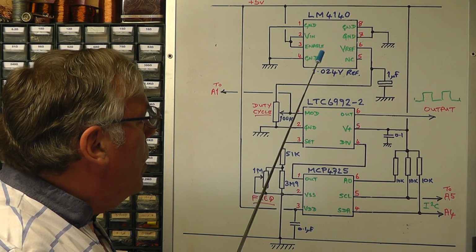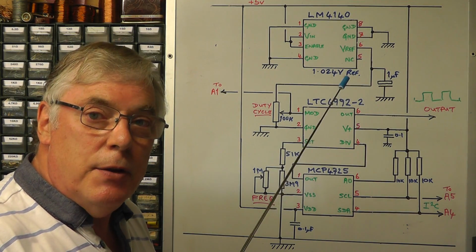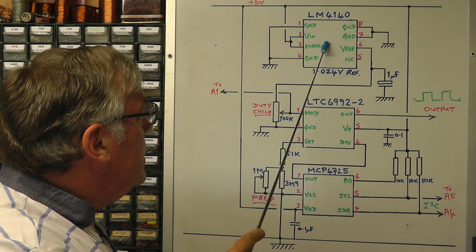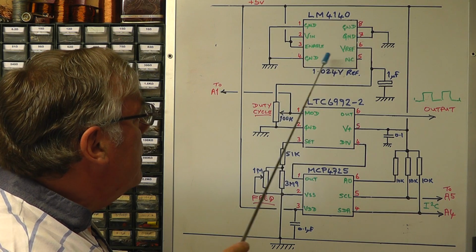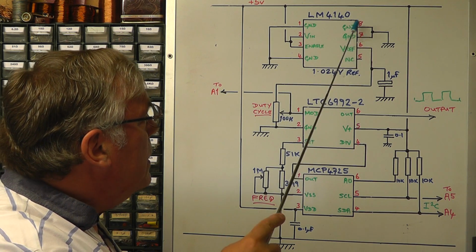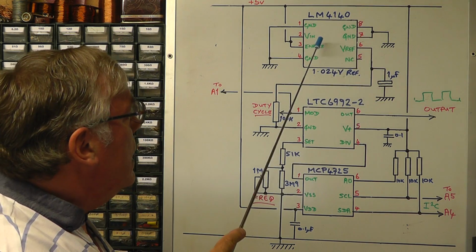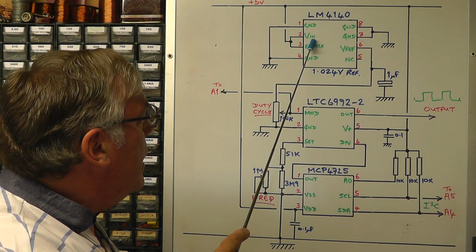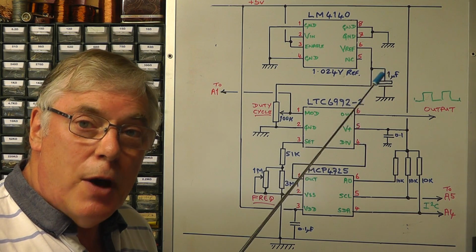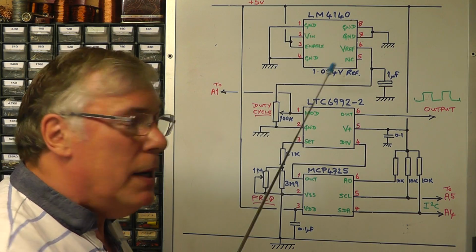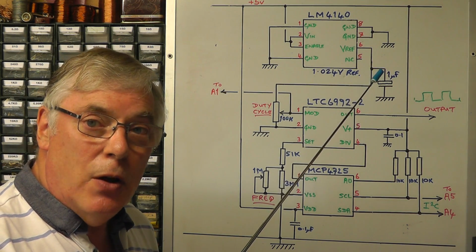Right, here we see a little bit more detail of the wiring for the three ICs for this project. There's the voltage reference IC, so I'm showing here the wiring connections for that. The pins 1, 4, 7 and 8 all go to ground. The V-in, voltage in for that IC, is on pin 2, and you'll see here that the enable pin we've strapped to the input V-in pin, and that ensures that the output is constantly on.